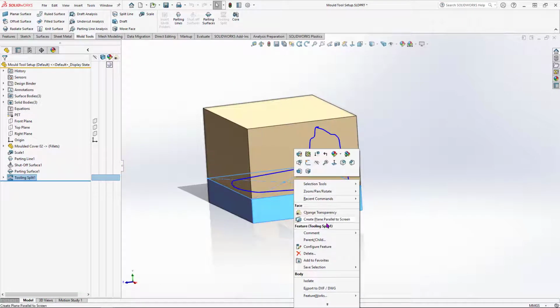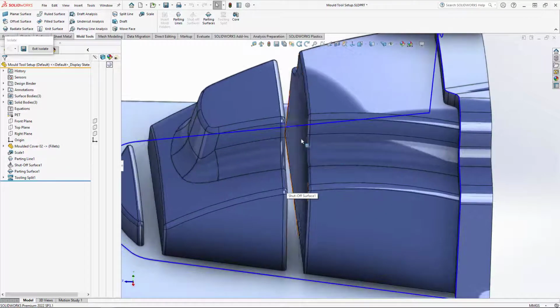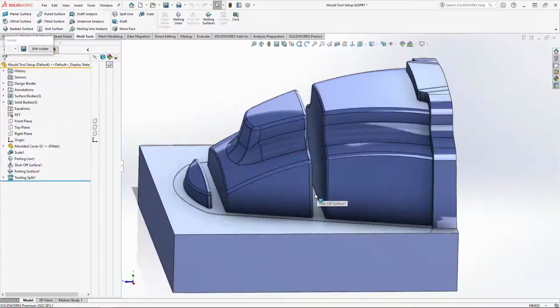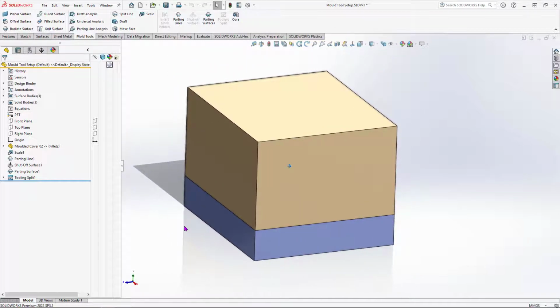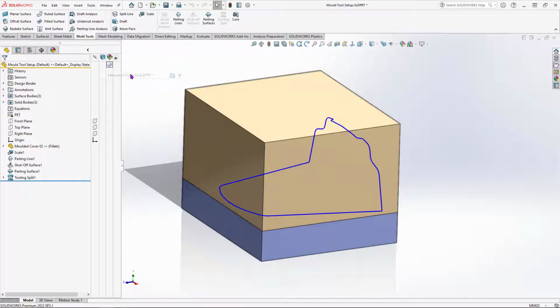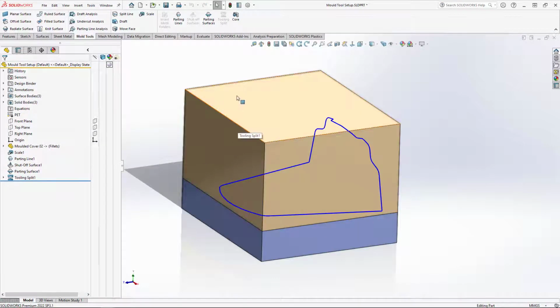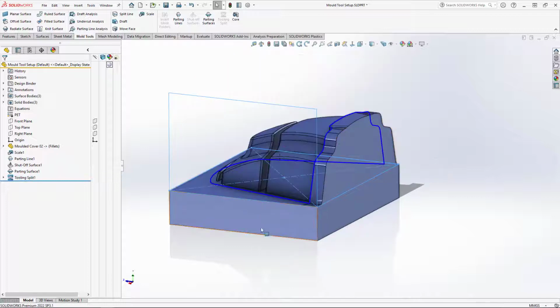And then if we isolate the bottom half now, that is what the bottom half of the mold looks like. So you can see the negative shape of the ribs. So that is where the rib features end up. So we've got the negative of the rib features in this bottom half of the mold. So this is how you build your molds inside Solidworks. You import the finished part into a new empty part, and then you create a parting line. So that's what the blue line is here, that represents where the split will be in your particular molding setup.